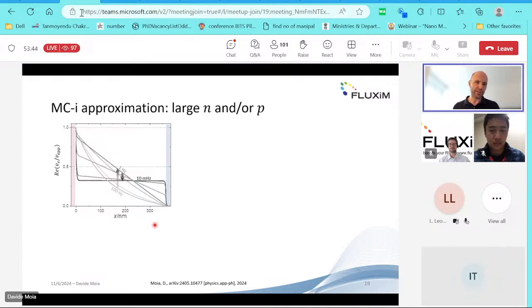Well, what happens in that situation is that at very fast frequencies, electrons and holes are able to respond to the applied bias. And what happens is that at fast frequencies, we don't have a linear change in electrostatic potential, but we have rather a slightly more complex profile.